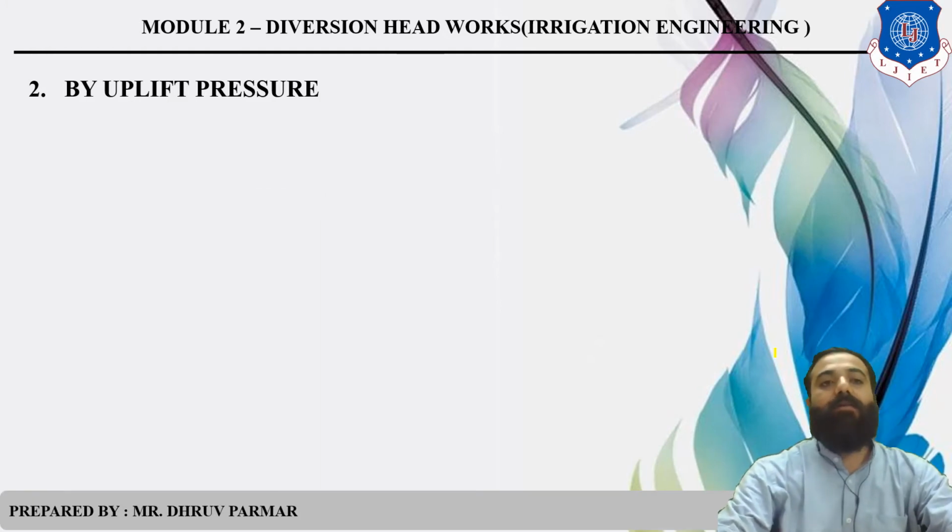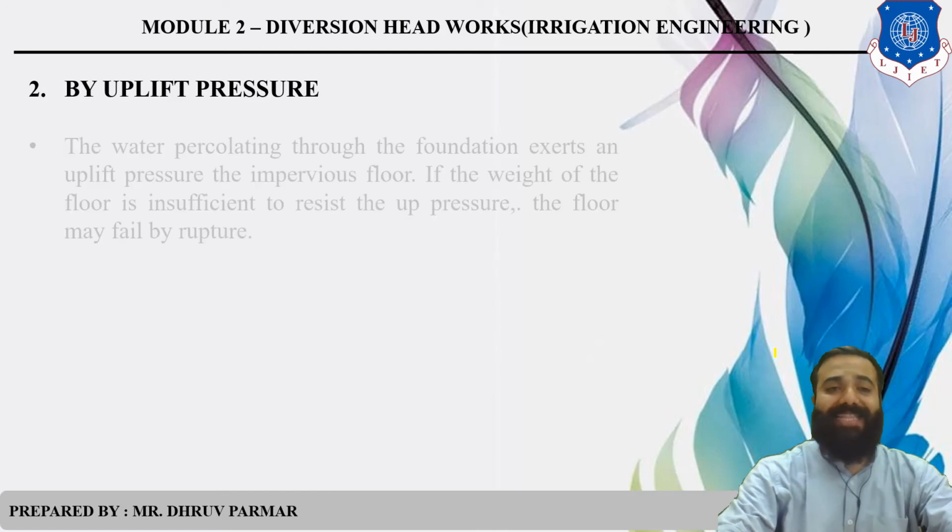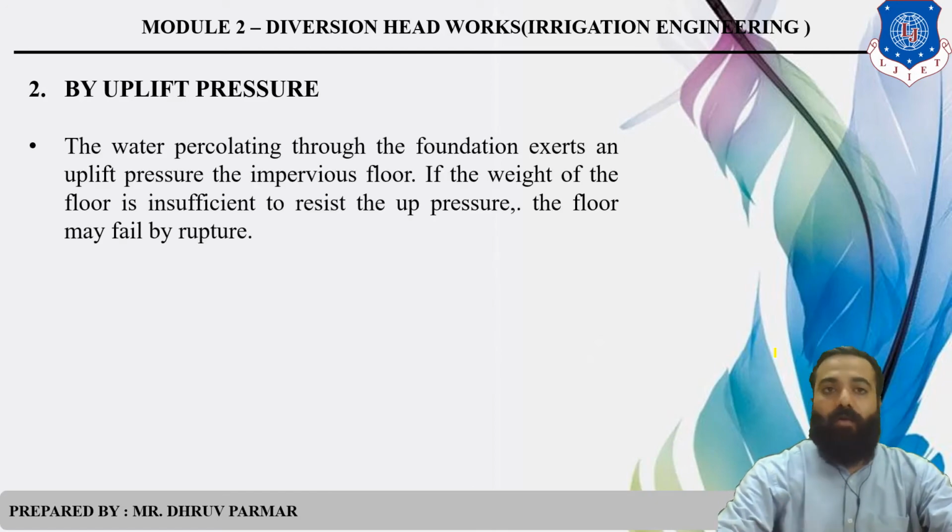The next one is uplift pressure. In these conditions, water percolating through the foundation produces uplift pressure. If the weight of the floor is not sufficient to resist the uplift pressure, the floor may fail by rupture.